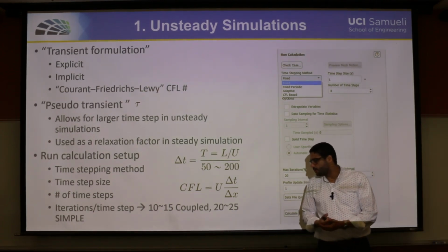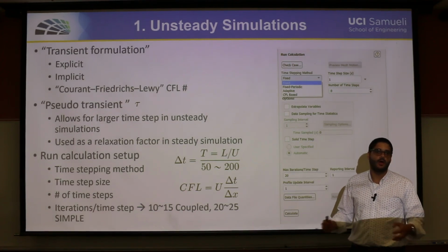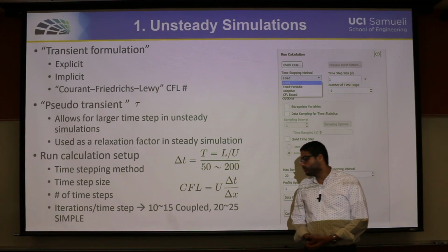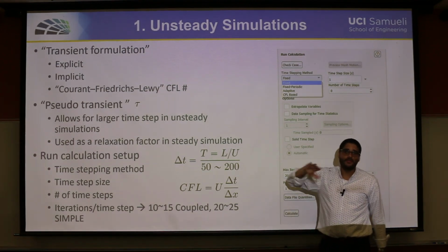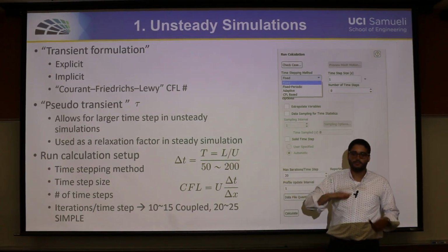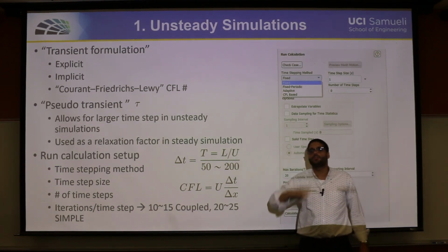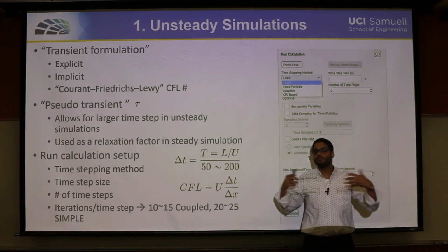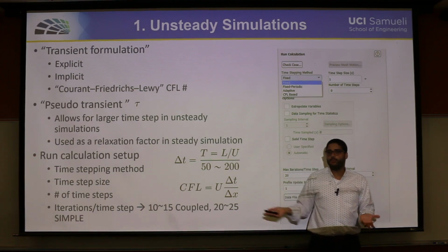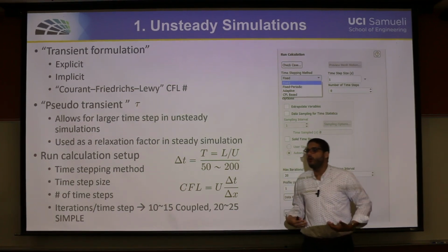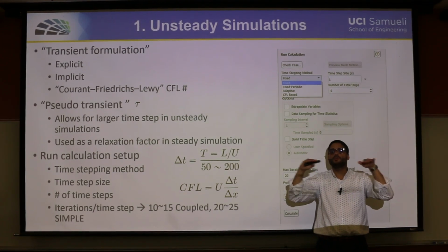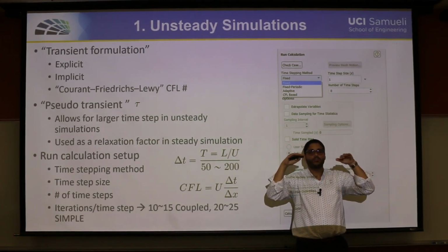I would like to hint about something that I have been noticing all of the time in performing CFD simulations. Remember the residuals last time, and I told you that please do not rely on residuals for judging convergence, because they don't give you a really scientific way of knowing what's happening. They just give you an estimate that you are converging, you are reaching a solution, but this should not be your convergence criteria.